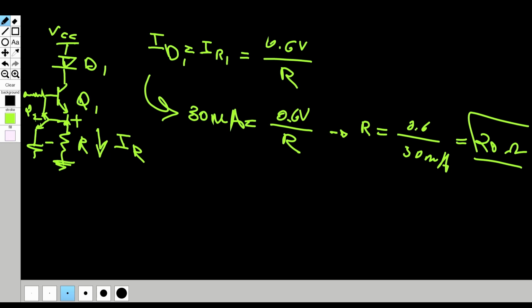So it's just saying that if we have a circuit where we have one LED, and then we have two simple NPN transistors, and maybe two resistors. I mean, this resistor R1 over here, it's good to have. It's not necessary. Like I said, if you're directly connecting it to an MCU, a microcontroller, microcontrollers usually don't supply that much current to their GPIO pins, so it wouldn't really matter anyway. But if you want to connect it directly, let's say you want this circuit to be always on, it's very simple, right?